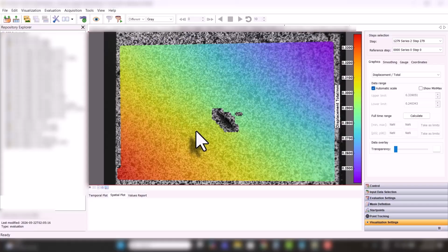But you can use AI to help you write a MATLAB or Python code. What the code is going to do is, you would start by, after running this correlation, testing out different settings and facet sizes for the full field. We're not doing any refinements, just the general full field. So you get the correlation you're comfortable with, the settings, and you run the full correlation for all images, and you export the full data sets for the full field into the big step files.